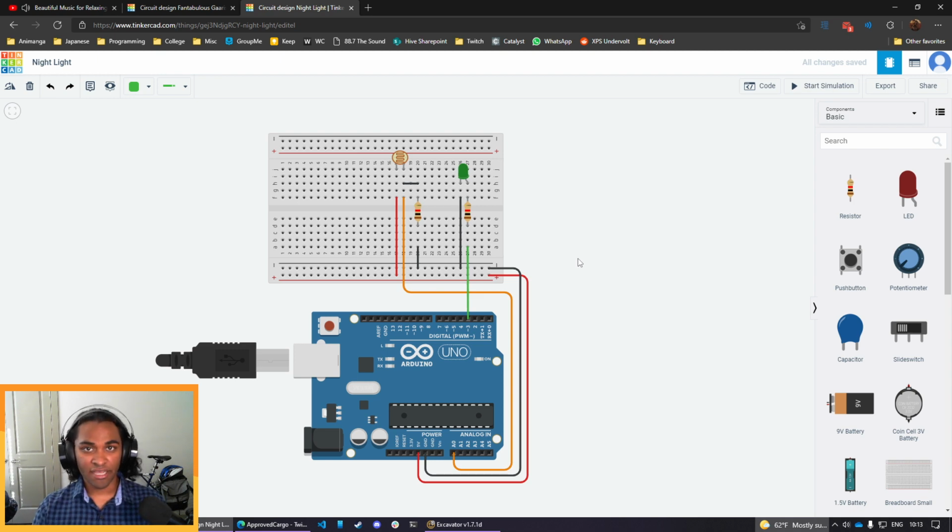Yeah, so this ADC, analog to digital converter. The one that's on board the Arduino will convert these voltages, 0 to 5 volts, into 0 to 1023. So you get 1024 possible values between 0 and 5 volts. Now, obviously, in real life, there is an infinite amount of voltage values between 0 and 5 volts, right? You can go decimals. You can go 4.5. You can go 4.0005. And that might not be accurately represented by the digital scale, but it's the best we can do in this situation. So 0 to 1023, we have 1024 possible values. That'll be important for later when we start coding stuff.